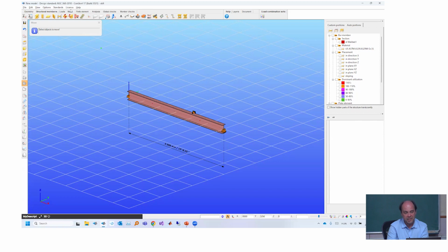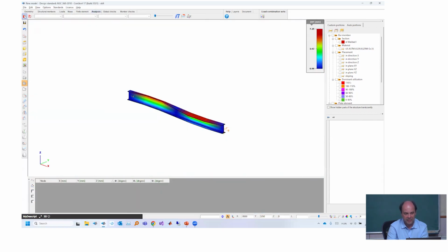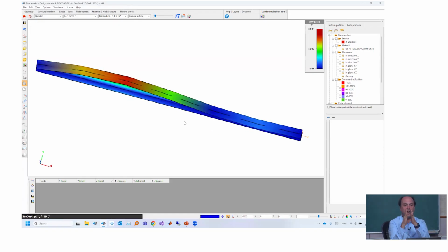And now it's very easy. Again, I just recalculate. I do nothing more. And now I come to a value. What is an interesting value? The two profiles would have a different end rotation, and basically the structure would need to break. Of course, the structure doesn't want to break. The two cross sections will start to play, and based on who is stronger, stiffer, we'll have an agreement finally on what is the equivalent unbraced length.